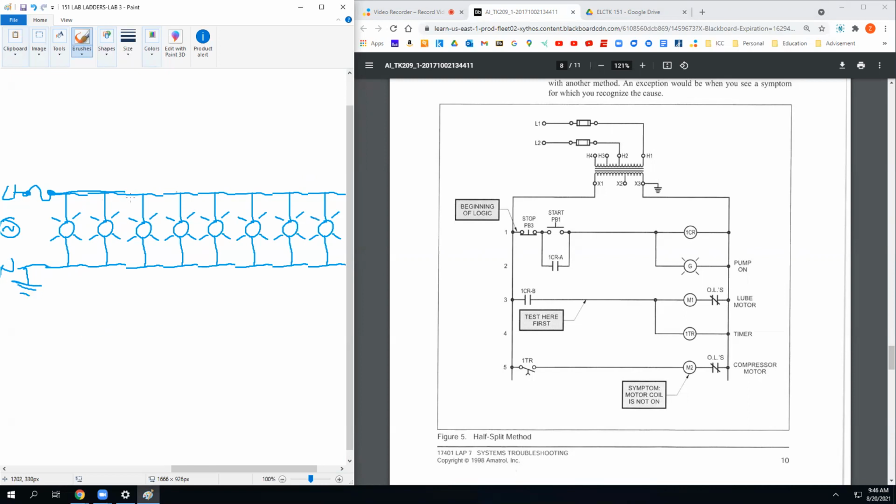And if this spot right here, for whatever reason, a wire's pinched, some mice are chewing on the wire, and it's touching something metal, this is grounded, causing this fuse to blow. Does everybody understand how that happens? And why that fuse would be blowing right now? You're providing 277 volts through that fuse, trying to feed all these lights, but right here, there's a leak to ground. Something is grounded that shouldn't be.